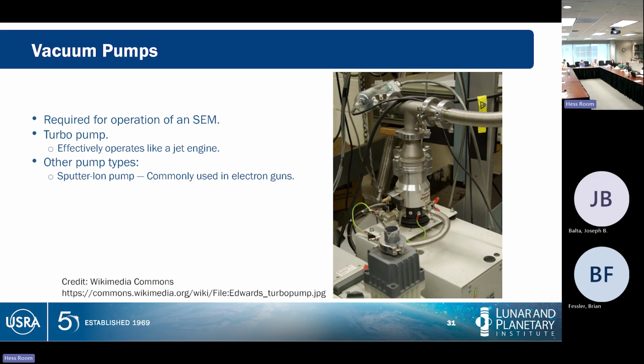Okay. Now, literally every SEM has some version of a vacuum on it. Almost every one has more than one vacuum, in fact. The fanciest ones are basically jet engines. A turbo pump on most SEMs literally spins like a jet engine to accelerate air out of there. The electron beams themselves often have an extra fancy gun or extra fancy vacuum that ionizes things and then pulls ions out of the way, because that needs to be held at a high vacuum, particularly on the field emission guns.